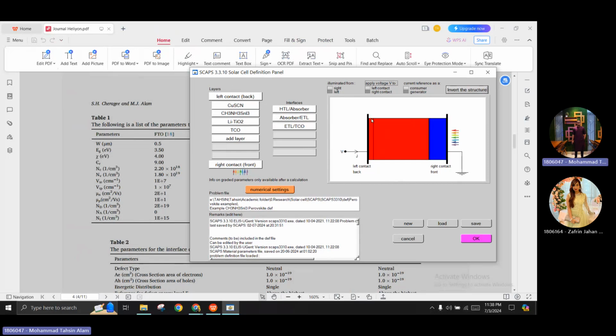So we know that after the junction formation, there are some exposed negative charges at the interface. So after the absorption of light in this absorber layer, the photo-generated electrons and holes, the holes will be attracted to this HTL side because of the exposed negative charges at the interface between the absorber and HTL.